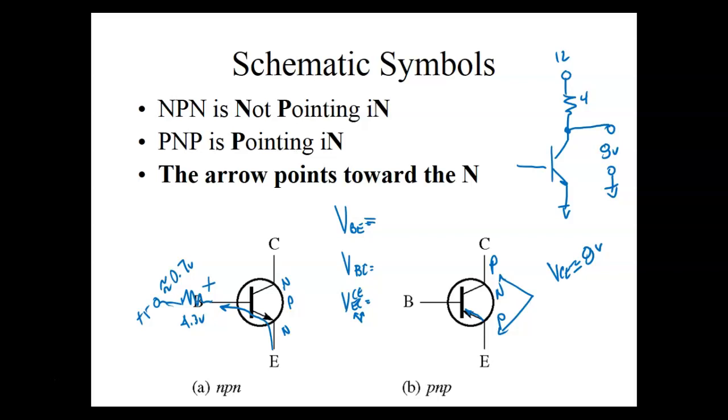Well, on a PNP, we would have to make the base negative. And this is why we say PNPs normally run on negative supplies. Now I'd have to put enough voltage over here, and I'd size a resistor right here to drop what? 4.3 volts at whatever current, we'll look at that later on.